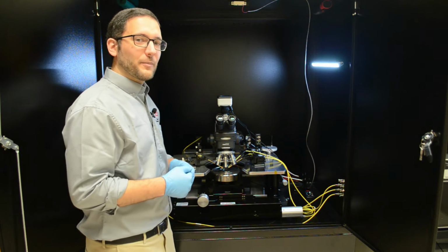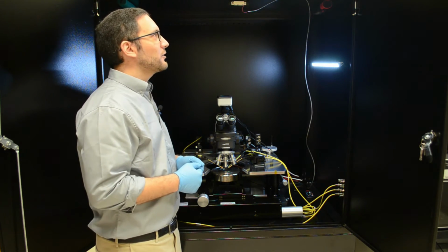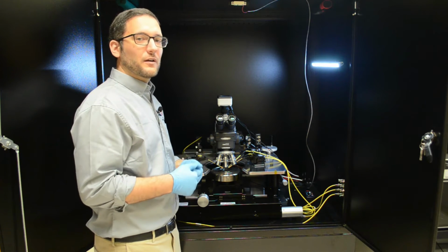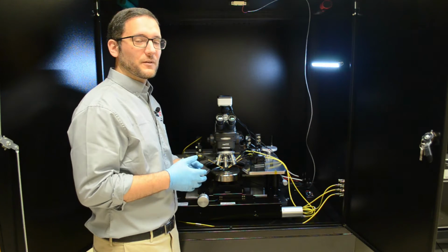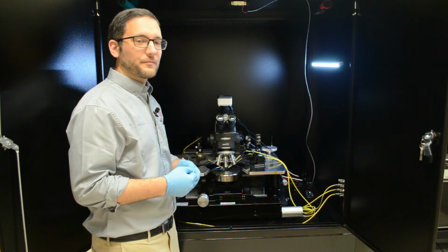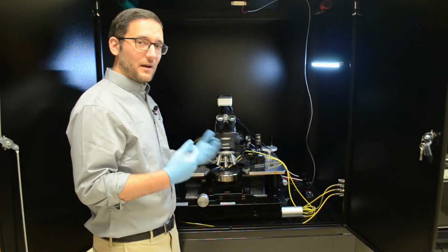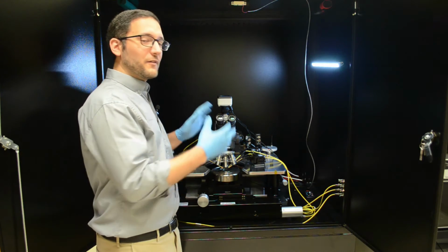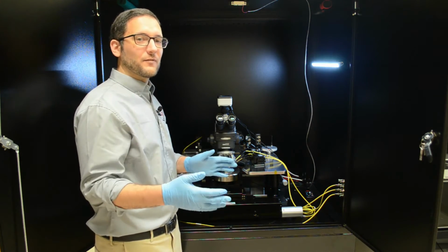Another interesting feature to pay attention to is the fact that we have an interlock. This interlock has been installed on the enclosure. The interlock serves to increase the safety of operating this system. And this is particularly important in high voltage applications that we use to test high voltage devices. High voltages can be dangerous to the operator, so we don't want the device to be live or active unless we know that the operator is at a safe distance.